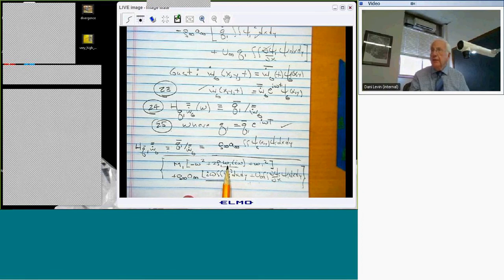For most aeroelastic systems, this term dominates, as you could compute it for typical values of zeta 1, omega 1, rho infinity, a infinity, and so forth. Typically, the aerodynamic damping overwhelms the structural damping. So even in gust analysis, you often neglect the structural damping. You got to have some damping in the system, because if I excite a system with a random input, which includes input in the frequency range where the resonant frequency exists, if I don't have any damping, the response is going to be infinite, right? So I need to have some damping, but it turns out the structural damping isn't the most important term.